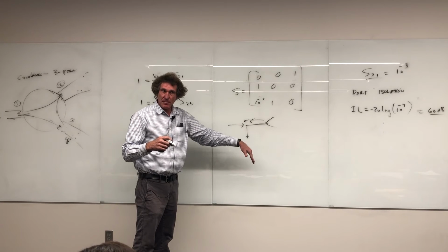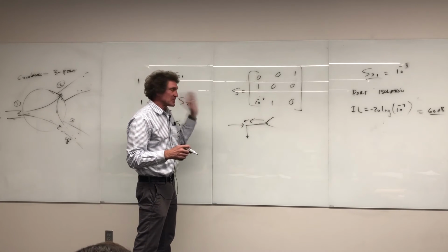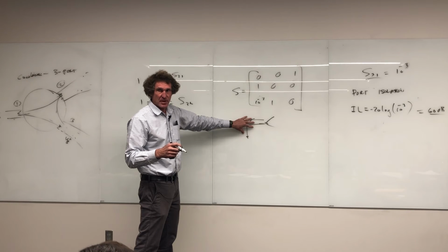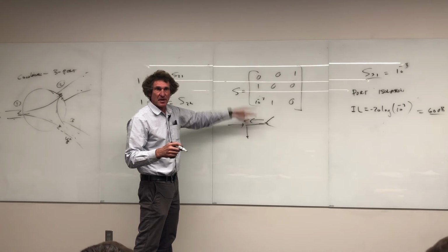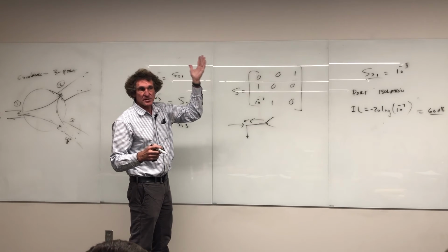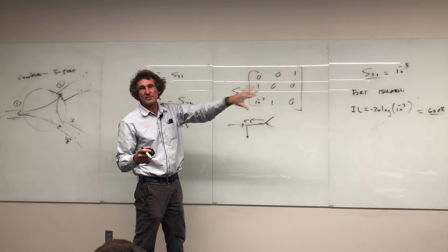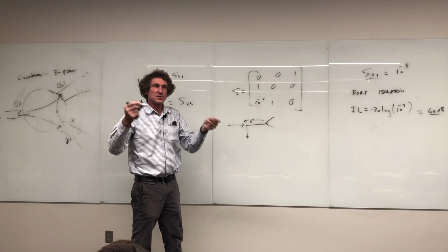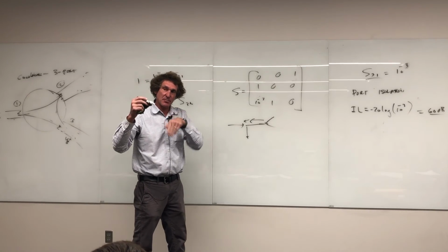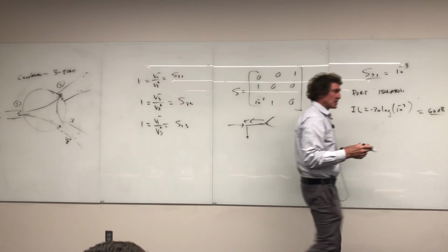And that's typically done that way, and it doesn't require any switch. There is no transmit-receive switch for something like this if you're using a single antenna. Does that make sense to everybody without going into all the details? How many understand that right there? All right. I'm not trying to make this hard. There's a lot of applications. This is one of them. For digital signal processing, there's innumerable applications where you get all these streams of data, and you want to make sure that data coming one way is processed a certain way, and data coming the other way is processed a different way, and that's what they use circulators for.